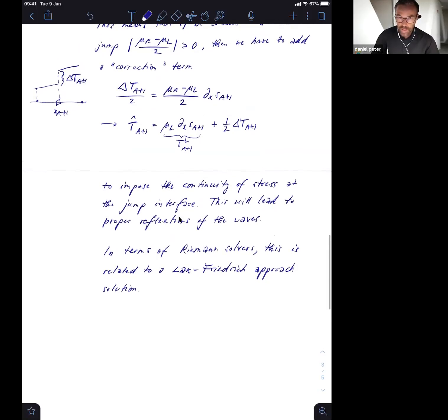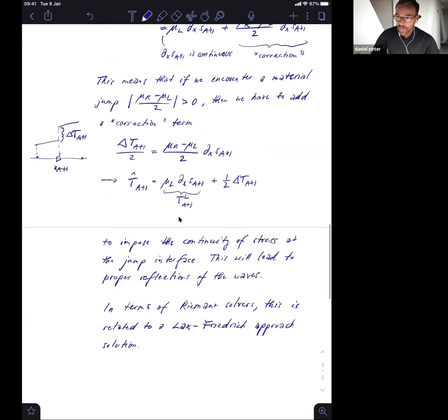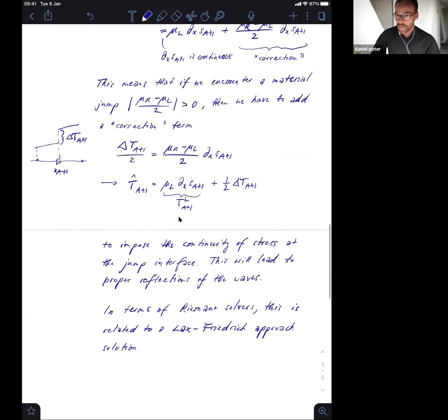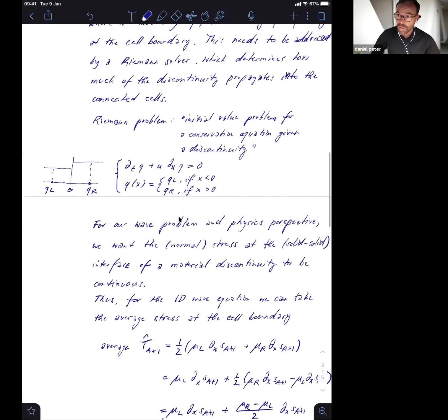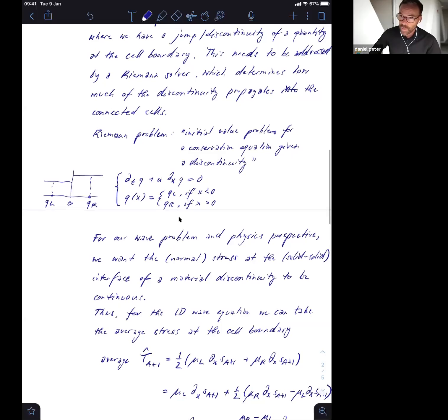So what I found funny is that if you look at literature about the finite volume method, it's almost always applied to first order PDEs. So you would look, for example, how to put the wave equation into a first order system of equations, and then you can recast it in this sort of advection problem, and then use the typical Riemann solvers for finite volume approaches to solve this issue with jumps at the interface, for example, when we have heterogeneous materials.